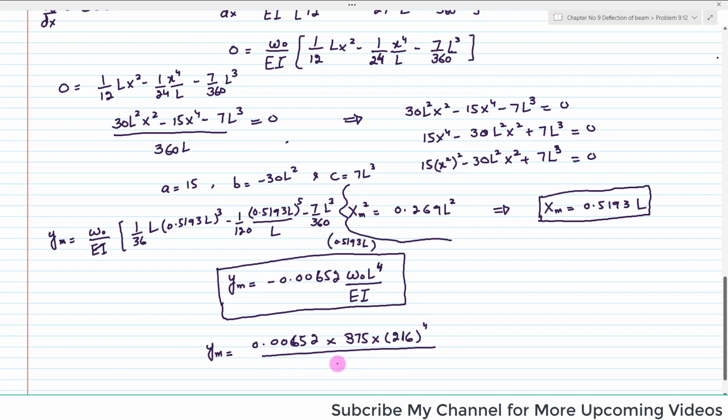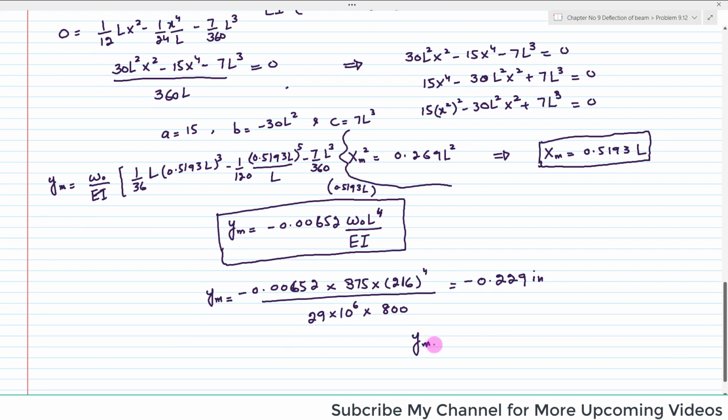Clear? Length was given in foot, so you have to convert it into inch. E is 29 into 10 to the power 6 and I was 800. So when you calculate it, it will be 0.229 inch and it will be a negative value. Negative means the deflection is downward. So the maximum deflection is 0.229 inch, downward. So this was the answer of part B.